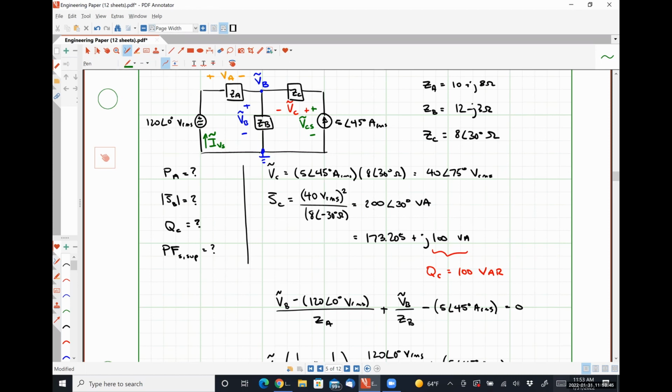Okay. All right. Did I say that's the power factor of each source? That's correct. So I would need the power factor of the voltage source and the power factor of the current source. We know the voltage of this one. We figure out the current by doing Ohm's law for impedance ZA, take the difference of the angles, and the cosine of the angle. For this one, KVL, so VC plus VB gives us the voltage drop. We already know the current. The difference of the angles tells us our power factor angle. Cosine of that gets us there. All right.